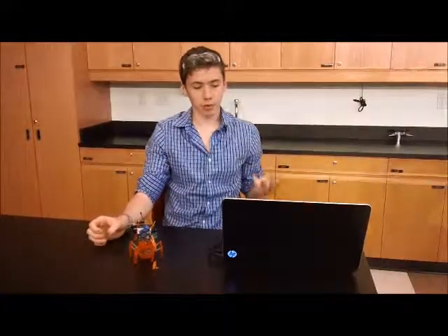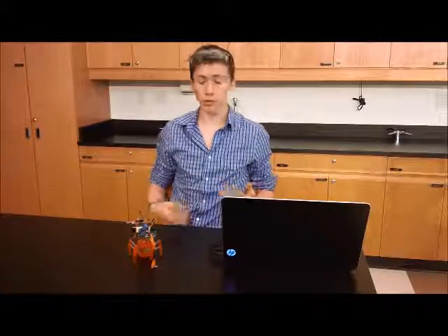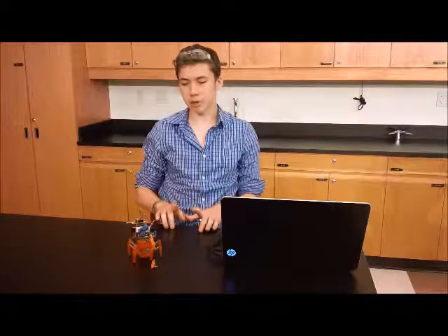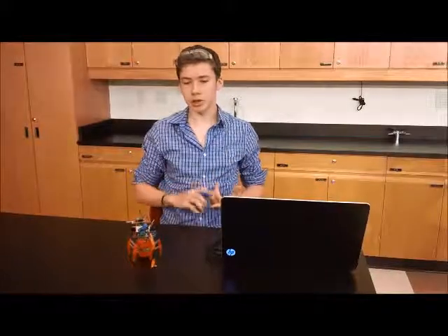And I've got a couple of different programs. I've got the original line following mode, and I've also got a mode where the user can essentially put in a speed they want the spider to move at and the distance they want it to go. I calculate the speed and the distance using a linear regression model that I created using a few data points, putting in different voltages.